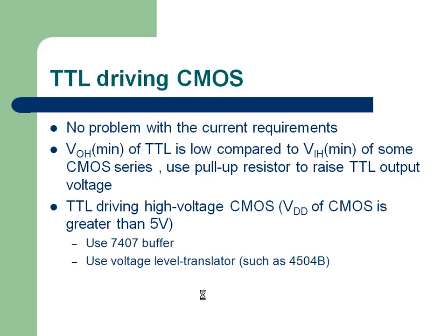So these are the inputs. VOH minimum, VOL maximum, VIH minimum, VIL maximum. This is the difference we are concerned about. So the driving gate is VOH. Its minimum value is not going to be important. Let us assume that this minimum value is small, and because of that you have a compromise on the noise margin with respect to CMOS.